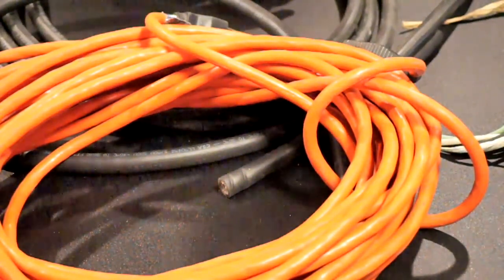Let's head back to the National Electrical Code now. All right, we've got them hung back up. So let's go back to the NEC, back to 400.5, which is on ampacity values. And it's going to tell us how to calculate these ampacity values on these different types of flexible cords that we've been taking a look at.